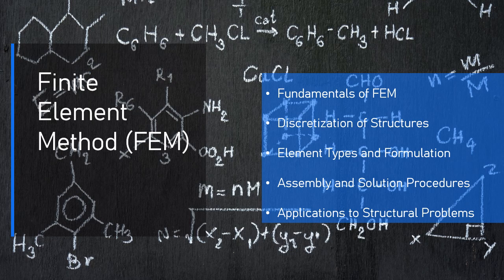4.1. Types of elements in FEM. Elements in FEM can be classified by their dimension and application. Below are the common types. 1. 1D elements, line elements. 1D elements are used for analyzing structures that experience primarily axial deformations, such as beams, trusses, and rods. These elements are defined by their length and can only deform along one axis.